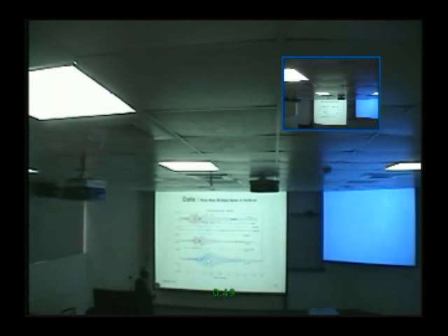Under the load of this truck, the bridge starts to get nonlinear, and under that load, the bridge is still okay. So this is the first time we can see how the bridge behaves linearly or nonlinearly. Under this load it starts to show nonlinear behavior. That is, the stress and strain start to bend, start to go into the plastic range.